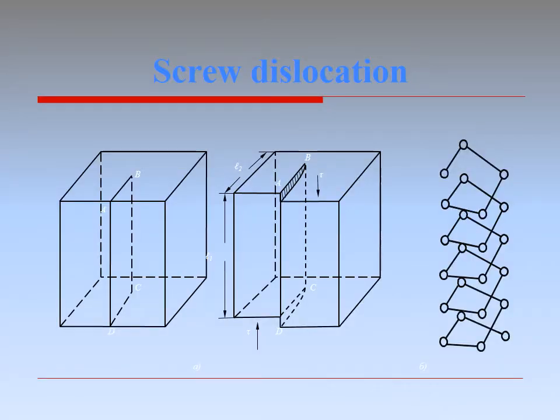The concept of a screw dislocation was introduced in 1939 by Burgers. Let's make an incision in the crystal along the plane ABCD and arbitrarily conduct a shift of the right front of the crystal down by one lattice period, as here.